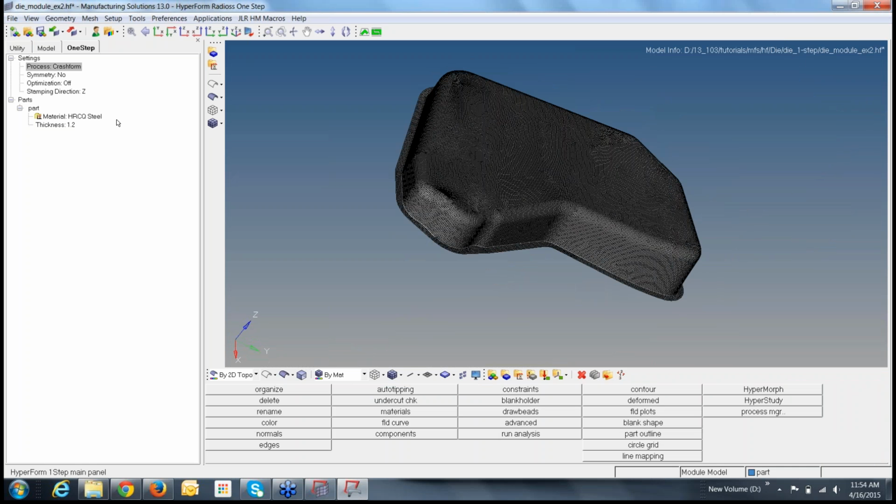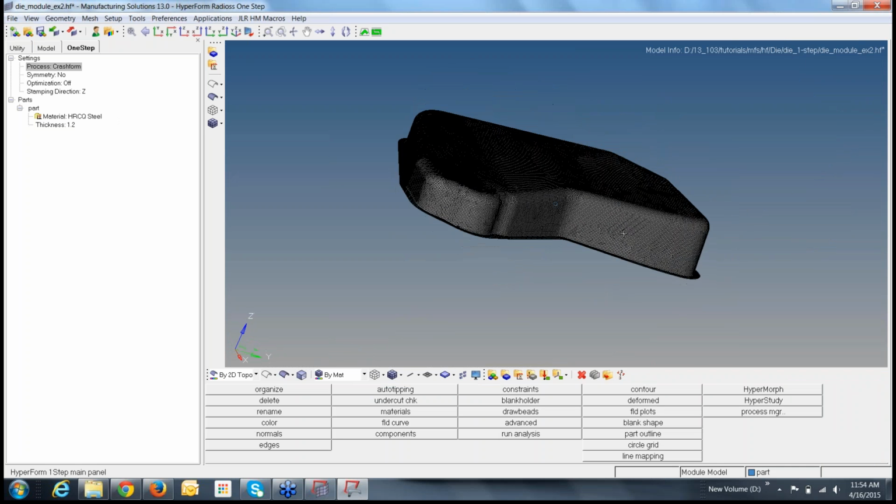How can you get rid of it is by providing some draft angle to this wall. This wall most probably will be 90 degrees. So you need to provide a positive draft angle, say of half a degree or 1 degree, such that this region will get formed plus also get easily ejected from the tool. This has to be done or modified in your CAD environment.